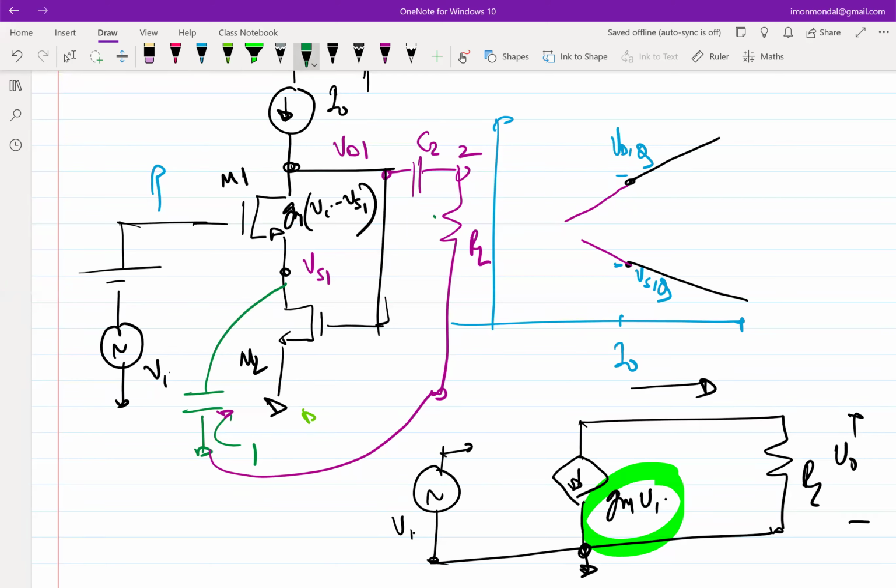So putting a capacitor has double benefits. We don't have to bother about biasing because it doesn't move the biasing voltage, no DC current, but it can potentially give you a very low impedance if you size it properly, right? If you size it large enough, at any non-zero frequency, right? So if C1 is kind of shorted, then let's look at the incremental picture. In the incremental picture, then, yes, we'll do. If I'm only concentrating on M1 for the time being.